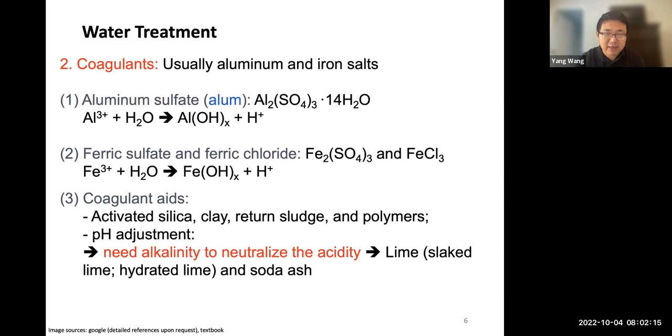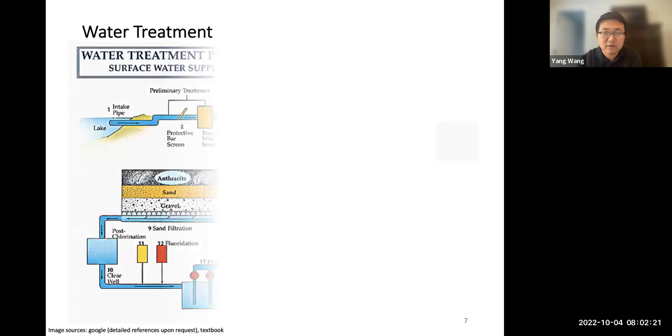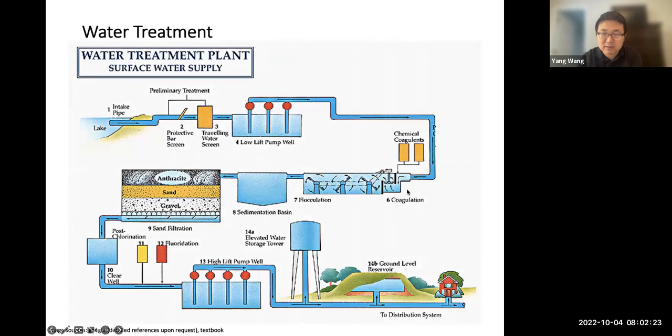So this is about the mechanisms, right? These are the chemical reactions. So how do we achieve that from the engineering perspective, right? Here you can see that we're separating them out into a coagulator and a flocculator. Okay, so this is a two-step process. It is not happening just in one reactor. The main reason is that there are different needs for, let's say, the reaction and different needs for settling.